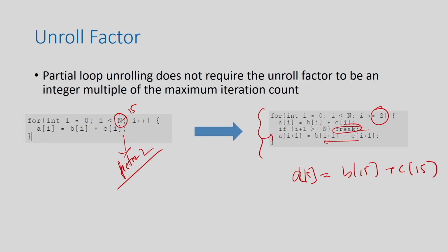Okay. So, basically the takeaway from this particular slide is, if you just put an unroll factor, you should not bother about whether it is exactly divisible or not, because even if it is not, the tool will make sure that you do not execute unnecessary things. It will stop unnecessary things, but it is an additional check. So, you try to factor it such a way that you should not have this kind of code, because whenever you add this code, it will always check a condition, which will take some resource and time. But it does not stop you from unrolling the loop.